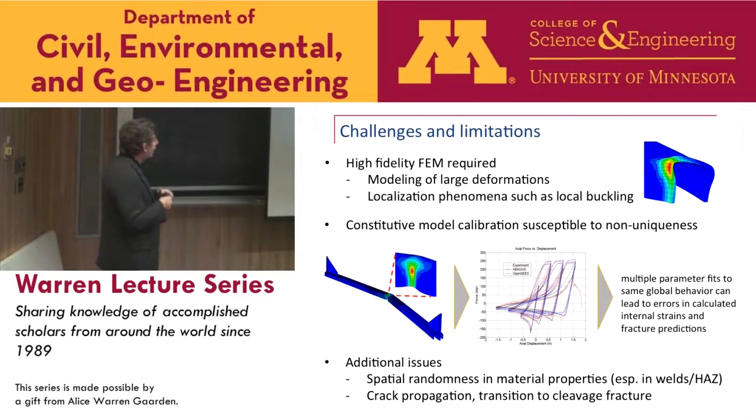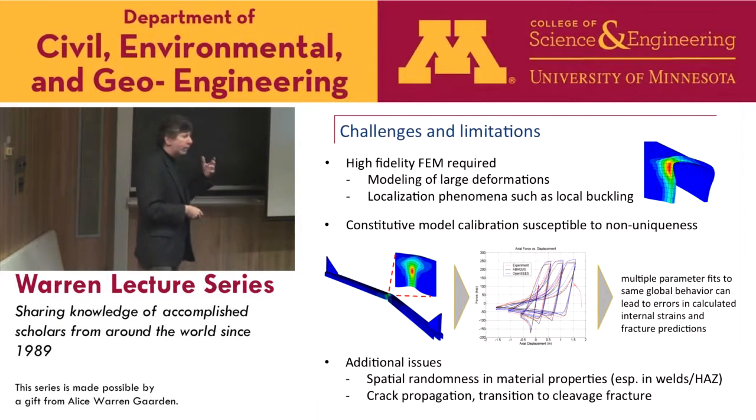So I think these models are kind of promising, but there's some challenges and limitations. First, because they are local models, and I think folks that have studied fracture for 100 years could imagine things like this were happening. But until recently, we have no ways to accurately characterize the stresses and strains at a very local level. You really need these detailed finite element models, and you need the computational power to run these models with 100,000 or more elements, because you need pretty fine models in there.